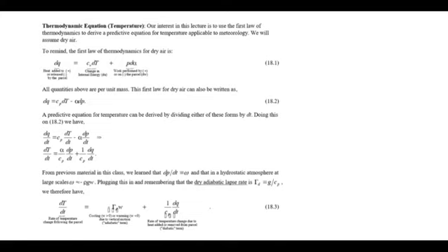So we have one for velocity. We have one for mass through the continuity equation, mass conservation, d rho/dt equals minus grad dot mass flux. You can refer back to that. What else do we have? We have one for any species concentration, for example, the change in pollution concentration equals the mass flux of pollution concentration. So anyway, there are rate equations out there.